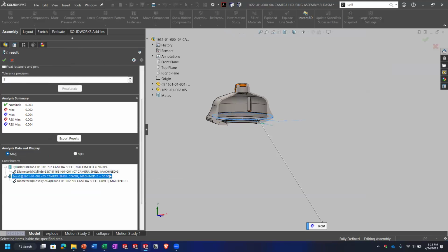So let's say I had 3 or 4 parts. One of the tolerances, the way things were coming together, let's say we had like a ±10 or 20 on some feature for some reason. And that feature alone was 90% affecting the tolerance, making it negative. Well, now I know what tolerance I need to fix primarily, right? Rather than spending much time trying to make that ±1 thou, it might be something else that just needs to be changed from ±20 to ±5. So yeah, it gives you all the major contributors here, which is really convenient.